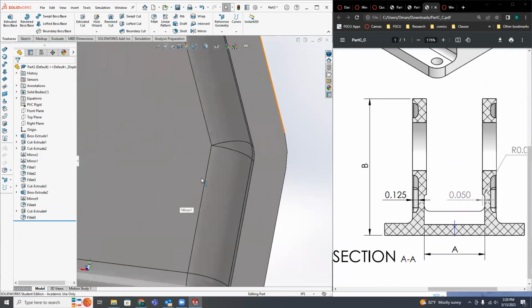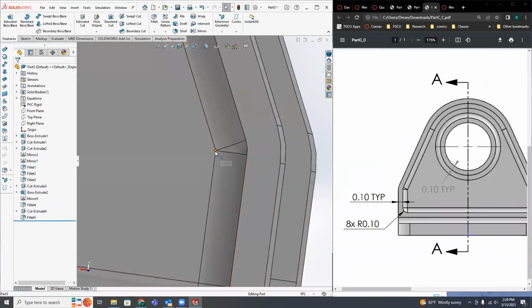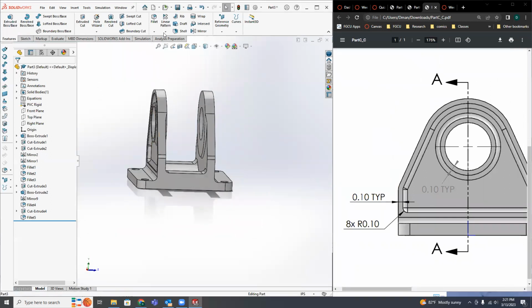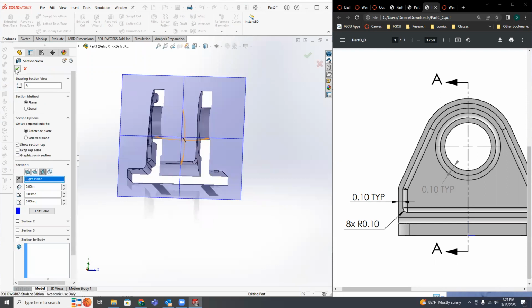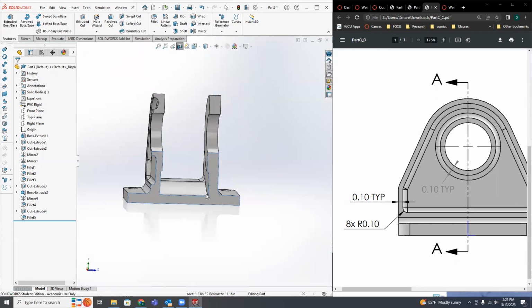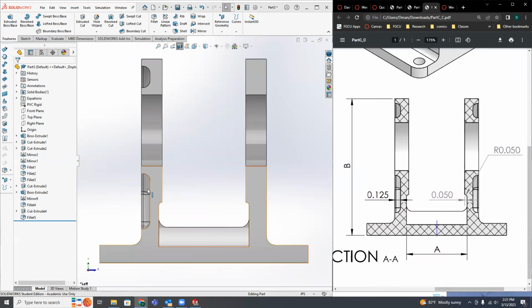And again, I can look and see, does this make sense by looking at how this sketch is given? You notice I do come to a point on here and I have a point inside this part. So that looks pretty good. And the radius of the cut, we'll actually go to a section view so we can see what this looks like. Go to our right view. Again, I compare the geometry of what I can see on there to what's given inside the part.